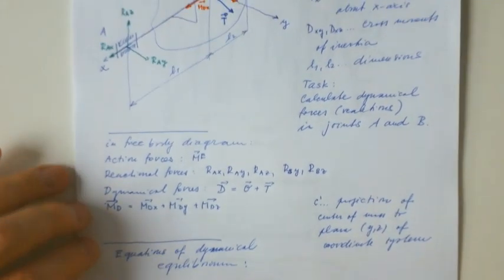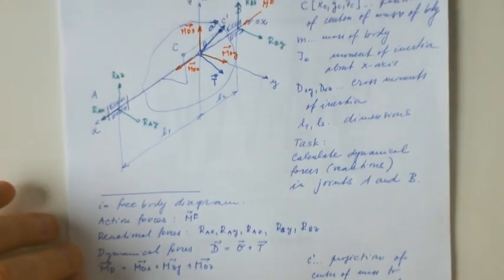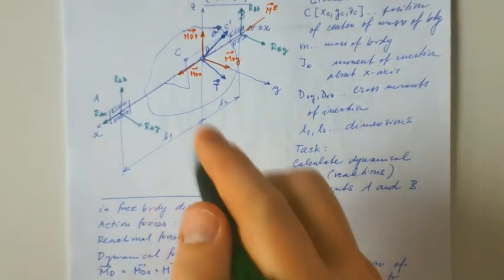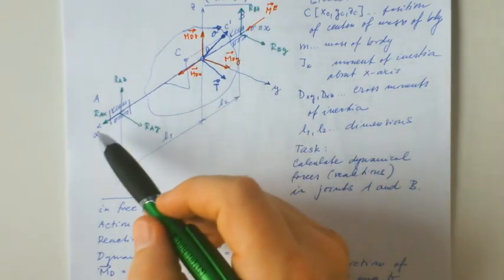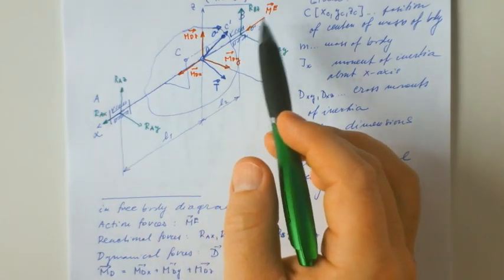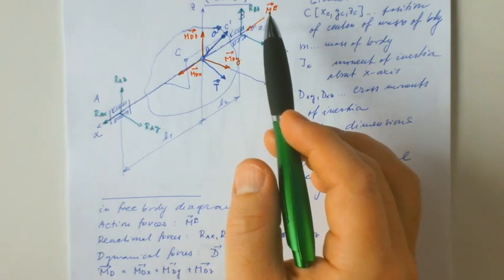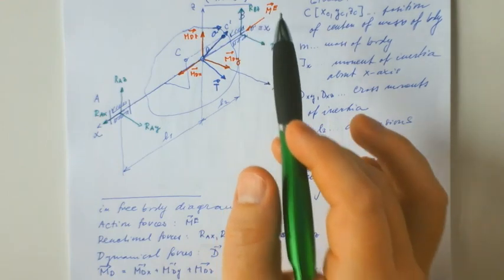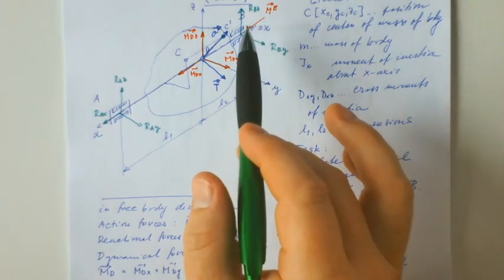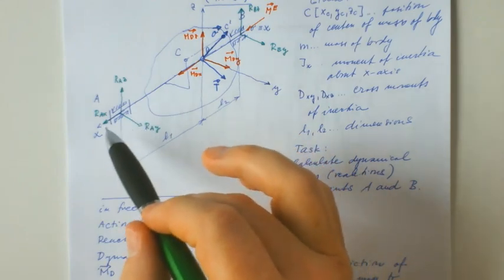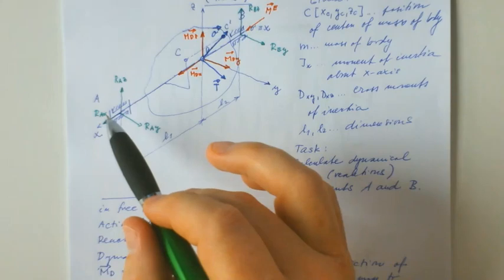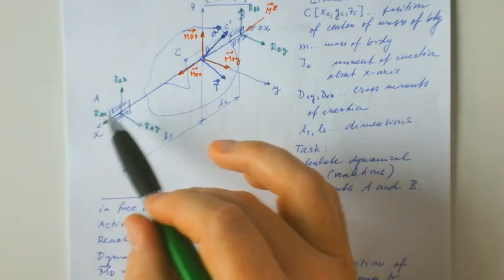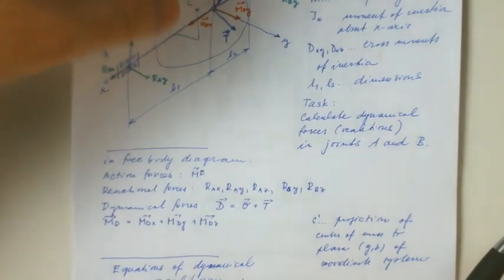You will not see directly, which is a bit of a pity, but let's see all the forces in x direction. So definitely it's not ME, it's not a force, it's a moment. It's a force effect, but not force itself. So the only force here is reaction force RAX. No other force is here.